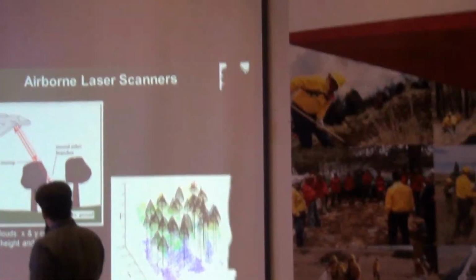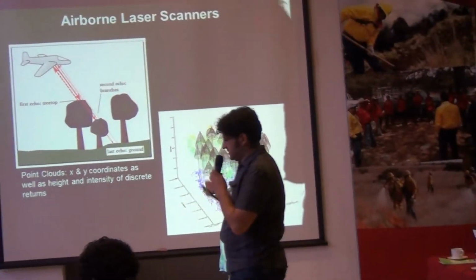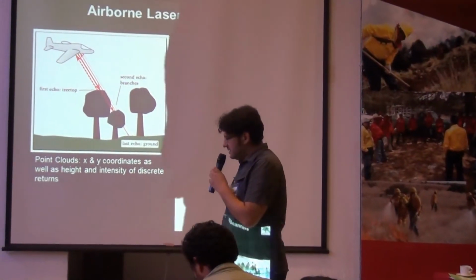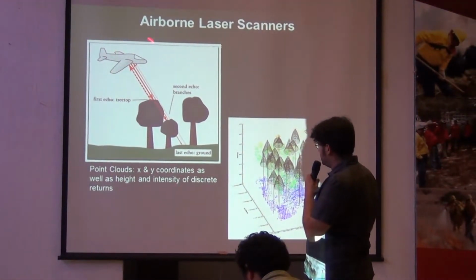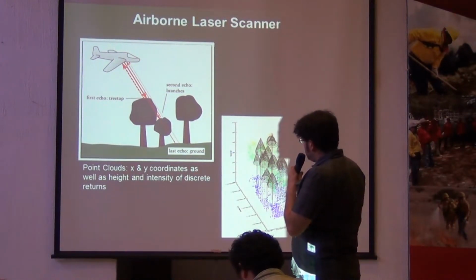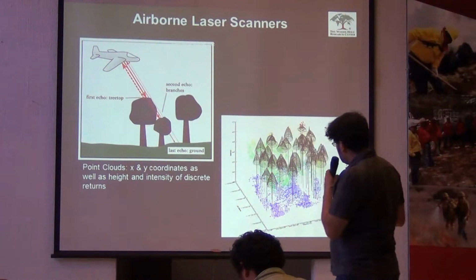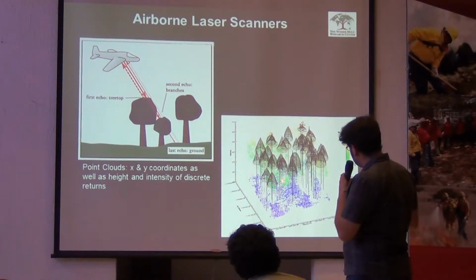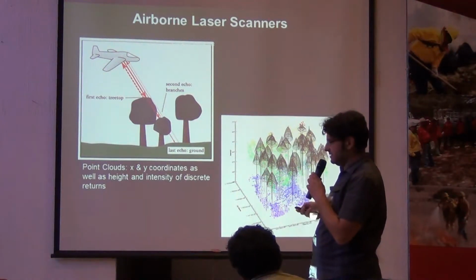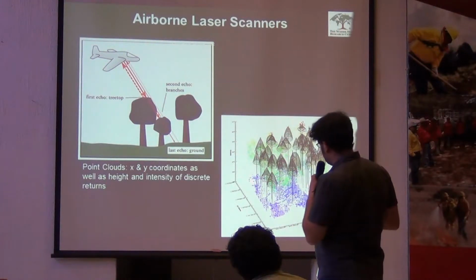In the last couple of years, LiDAR data has become very popular for mapping forest structural attributes, and in particular biomass. In particular, airborne laser scanners have been used a lot. Airborne laser scanners, as already said, usually have sensors mounted on an airplane that send out LiDAR signals and measure the time the signal needs from the sensor to the forest and then back. That gives a three-dimensional impression of the forest. These returns, you see here, these points, reflect the vertical and horizontal distribution of the tree constituents, the leaves and the branches. And that's a very powerful tool for estimating forest biophysical parameters such as biomass.